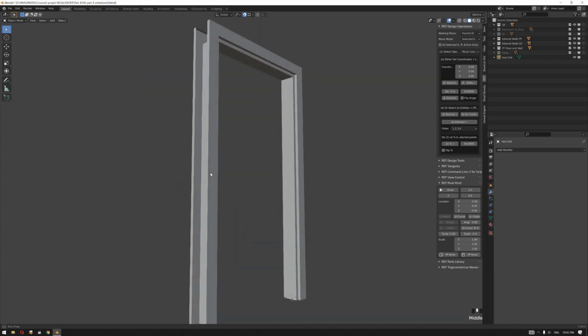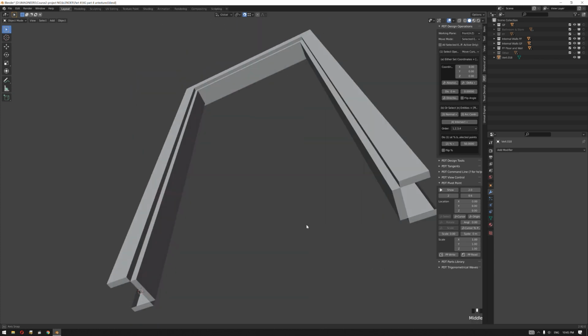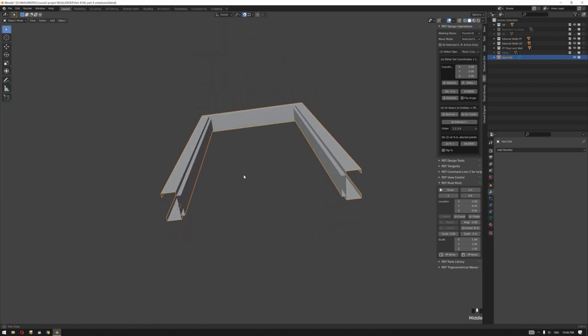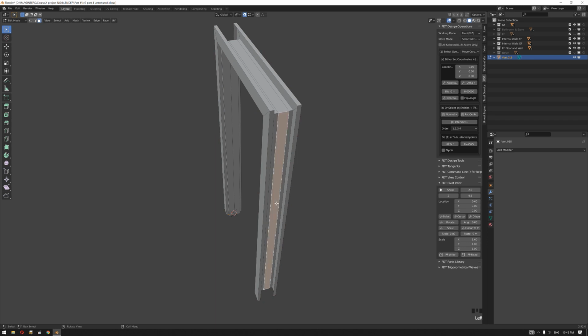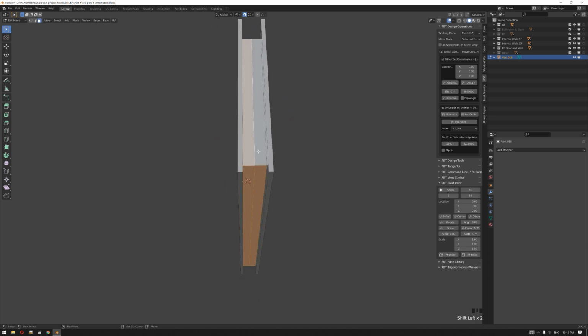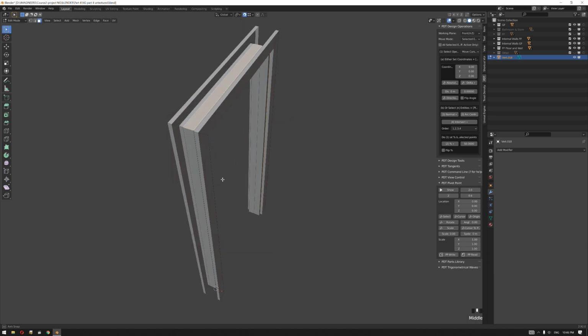Now it is really important to delete the unnecessary faces that will not actually be needed, because they will not be visible inside our model inside Unreal Engine. So we're gonna remove all of these faces. This is gonna be also helpful in the time of unwrapping the model. So these faces also are unnecessary.